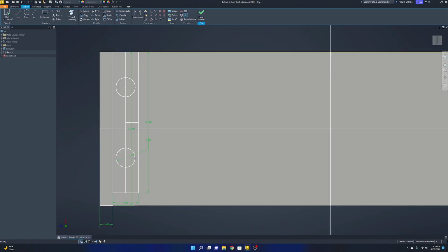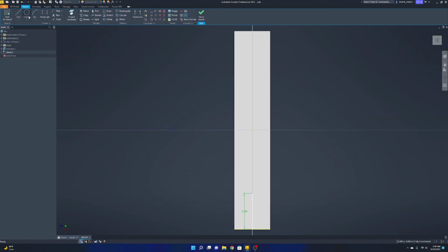And remember the diameter of our circle is 1.5 inches. So I'm going to create a circle. Actually, create a line. Sorry, a line, and we're going to write 1.5 divided by 2, so we get 0.75 of an inch, and we just draw a circle from there to there. And then I'm going to draw a line across from here, and mirror that across. I'll click on this mirror line button, hit apply, and OK.